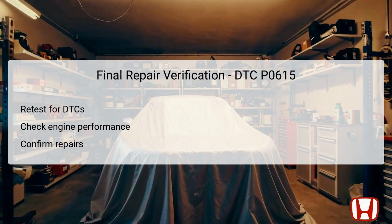After completing all necessary repairs related to DTC P0615, it is essential to conduct a final verification to ensure that the vehicle is operating as intended. Start by retesting for any diagnostic trouble codes using the HDS to confirm that DTC P0615 and any other related codes have been cleared from the system.